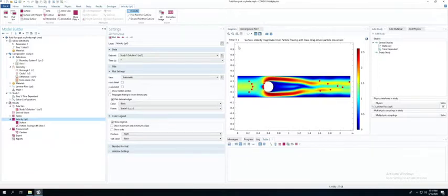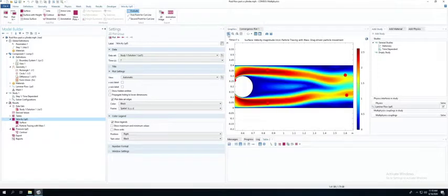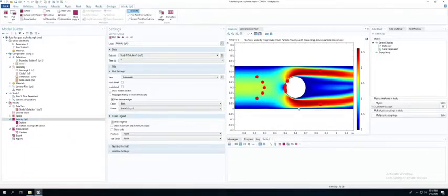We're going to zoom in a little bit here to give you a better look at the details. What I want to do is draw a cut line across this section of my pipe. I want to take an average velocity from the edge of this stationary object to the edge of my pipe, and calculate what the average velocity of the fluid flow coming into that pipe is.